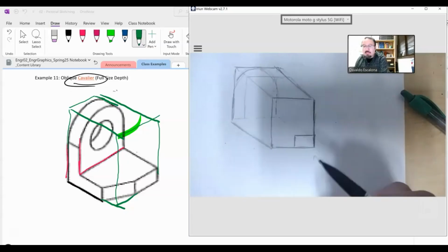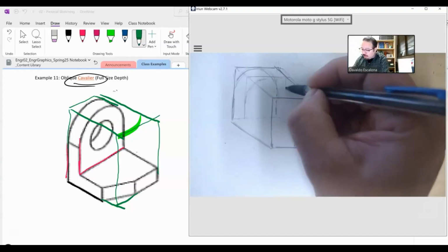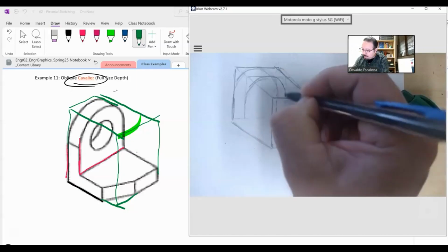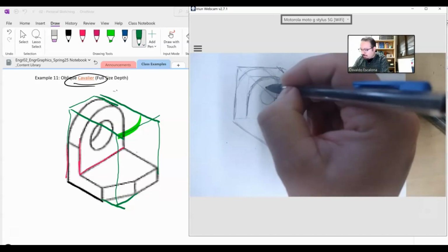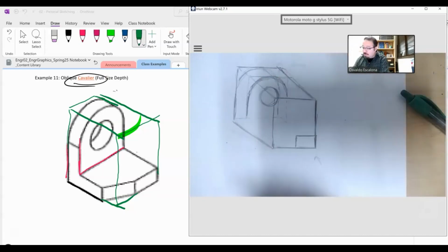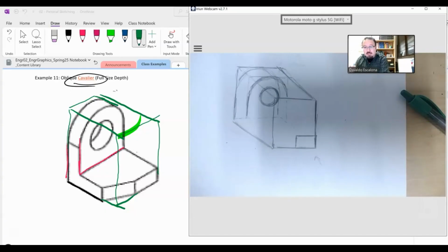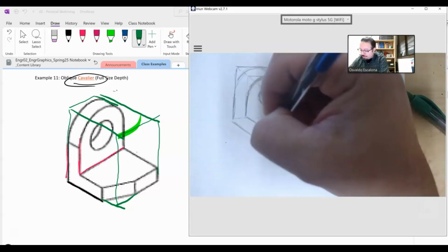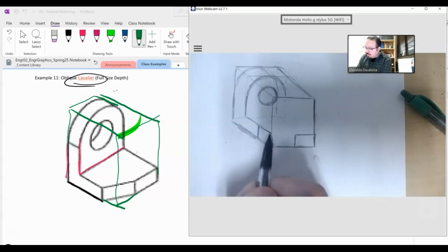How do I know this? This is because I have the oblique drawing. I mean the isometric view drawing that tells me the true size. So I can do the same concept if I were to create a plane that is projected. It will look like this, right? I can also go and make a circle. I show you how to do the circle, right? You guys look for the bullseye. Once you got the bullseye, you can divide it into diagonals, divide the line into 3, and so forth. Look over here. In terms of this distance, that's what you will measure in your isometric view. They come over here, and go sideways, boom, boom, boom, right?